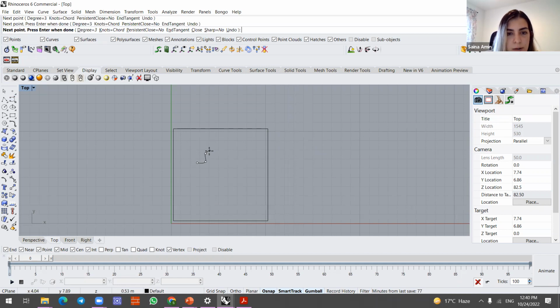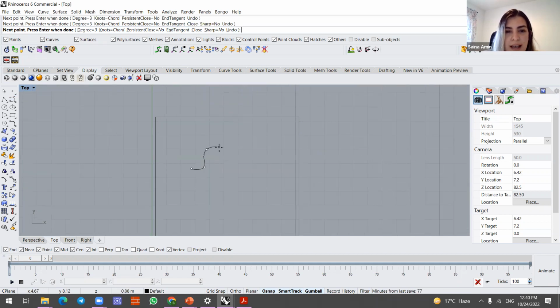And now you know the concept of the closed mesh or open mesh, and when you go for creating the line, you can think about the further steps and think about the whole joins and connections between your lines. For example, when I start to do the top of the contour, I'm thinking about the closing now, because in a further step, if I don't pay attention to it, it would make some problems for me.